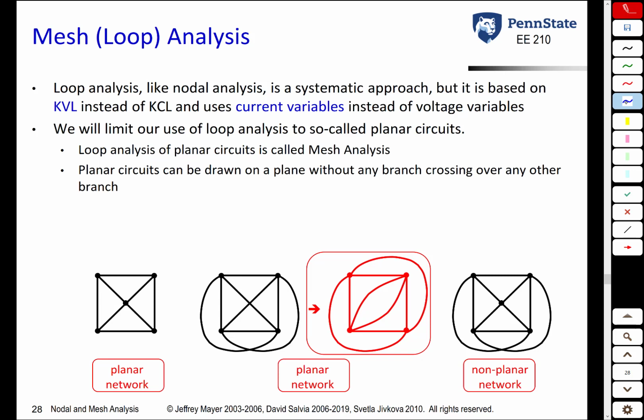In circuit analysis, there is a general technique called loop analysis, and there's a subset of that called mesh analysis that we're going to be using here. I'm not going to talk about more general loop analysis. We're talking specifically about mesh analysis. Mesh analysis is limited to circuits that are called planar circuits. A planar circuit is a circuit that basically could be drawn on a sheet of paper without coming out of the paper at all. Loop analysis of planar circuits is called mesh analysis, which is the technique we are going to be covering here. So let me explain a little bit more about planar circuits.